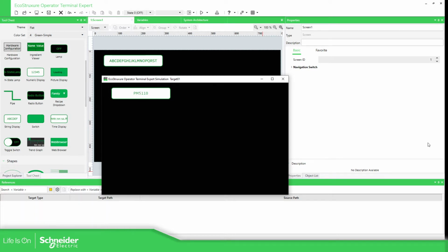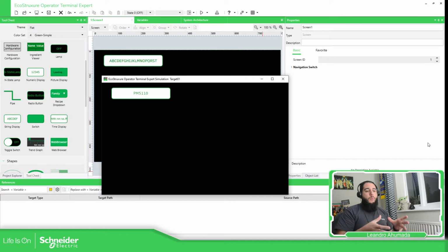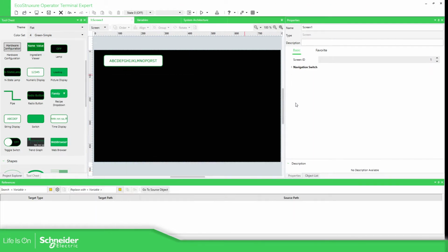So what we have done here is to read the bytes for the alphanumeric data type that we have on the power meter, move the values of the %MW of the IO scanner into %MW values of the PLC, so I can read from an HMI and define that variable as a string, so I can really see what is the content inside that. So this is for the UTF-8, if I'm not wrong. Now let's continue with the next one. I'm going to close this.